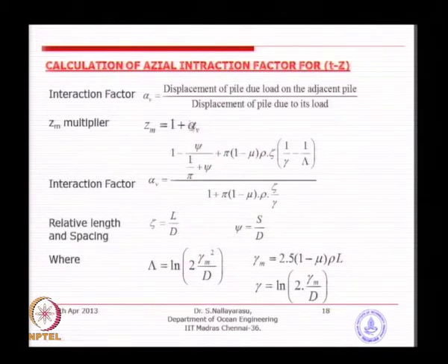So, that much increased deflection will happen depending on the spacing to diameter ratio, the length to diameter ratio, and then the Poisson's ratio and the increase in the soil modulus value below half depth. Basically, if you look at these parameters, what else is unknown?